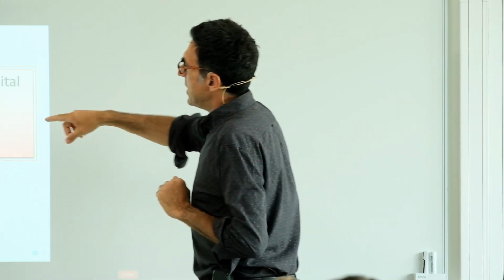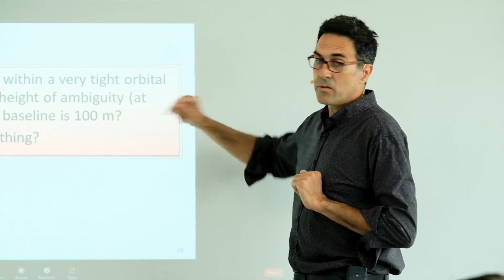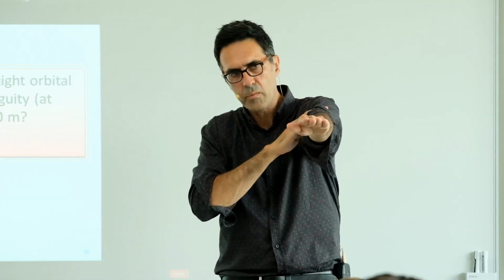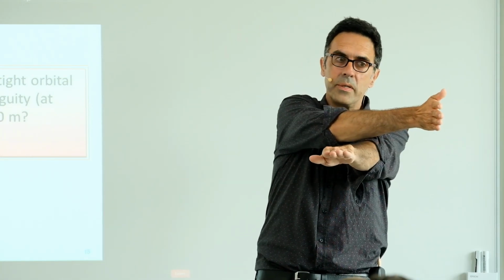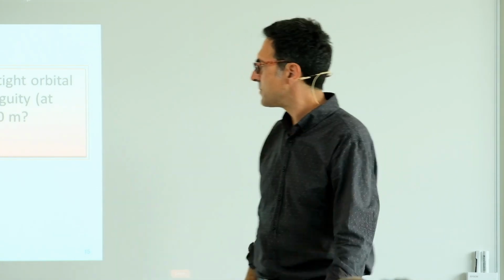Now, this range in which you can go, you can decide. You can say, well, I'm going to let it drift for 1 kilometer, and then I'm going to steer. Or you can say, well, I'm going to already steer much faster. The consequence, of course, if you have a satellite and a very big antenna and you fire the thrusters, the whole thing is going to wiggle, right? Because it's like if you pull the brake in your car, you know there are accelerations, so you don't want to fire these thrusters too much. So here the choice was made to have a maximum baseline of 100 meters. So if this is the nominal orbit where you want the satellite to be, if it drifts over 100 meters, you fire the thrusters and go back to minus 100 meters, and the zigzagging is limited to this range.